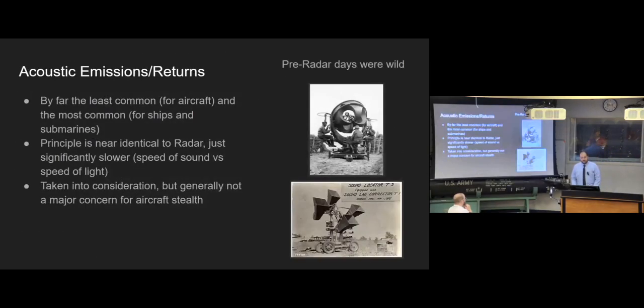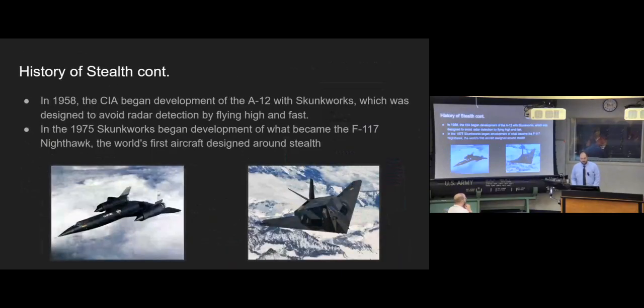And one of the earliest ways that they did that is right here. It hampered performance. It was a trash vehicle, but this was covered in grates, which were coated in radar-absorbent material. And the grates were sized such that they would functionally act as a Faraday cage to the frequencies that they were worried about. But that's why this thing flew slow. The airflow it needed was not present.